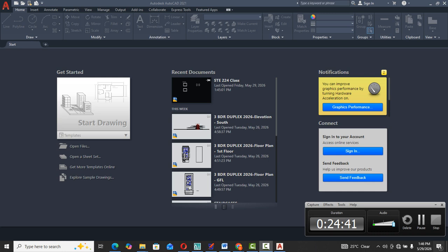Now, let me introduce extend. I want to extend this line to that place. To do extend, I choose boundary edges. So I'll say B, enter. Then I select the objects. You see, I'll say enter. So I can go and do the trim I wanted to do again.